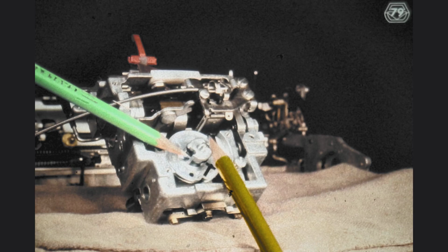The other end, the outside end of the spring, is fastened to the spring cage. We remember from fundamental mechanics that a spring must always be held at 2 points at least. The green pencil indicates a small anchor spring. It is the point at which the spring cage, and thus the outside of the rotate spring, is locked onto the frame of the rocker. Since the rotate tape is connected to the rotate pulley, which is free to rotate, we conclude that the rotate tape is kept taut by the force that comes from the rotate spring acting on the pulley at the point indicated by the yellow pencil.